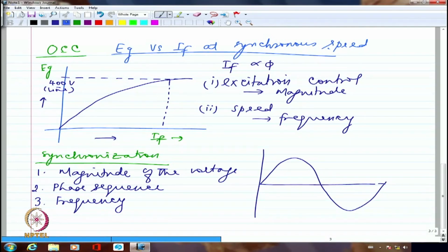If I have another one at 49 Hertz, I will have basically the phase shift between these two slowly and steadily increasing. I hope you understand. One waveform corresponds to sine omega 1t. The other waveform corresponds to sine omega 2t. So the difference, omega 1 minus omega 2 times t, is going to keep on adding further and further as the time progresses.